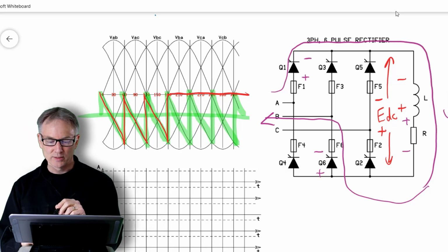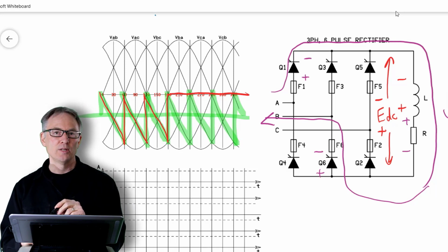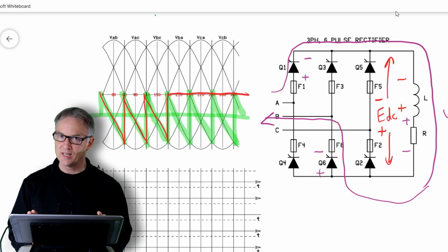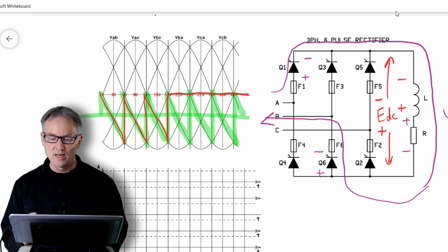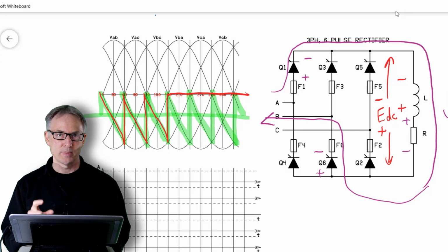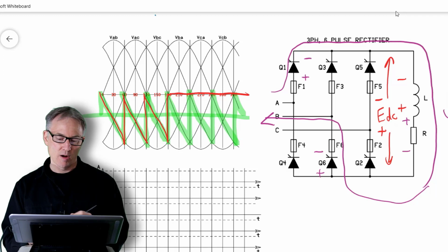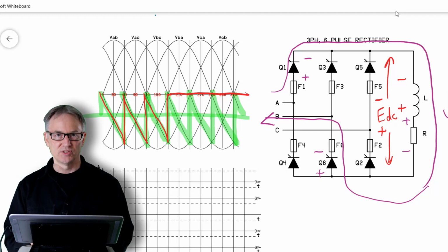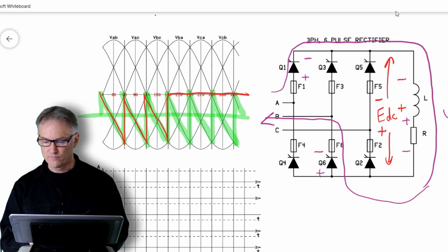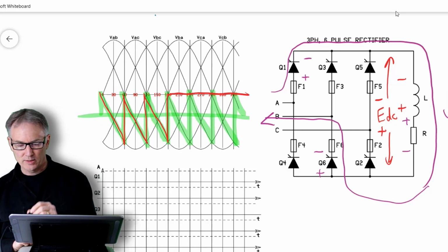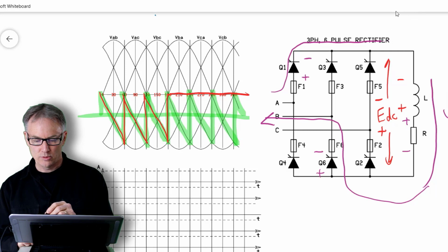So again, the inductor is what's providing a temporary energy source to maintain forward conduction. So irrespective of whatever the AC voltage is at that moment, the inductive volt drop is negative enough to keep the net polarity on the SCRs forward biased until such time as the current collapses to 0. Okay? All right, let's do some other stuff.